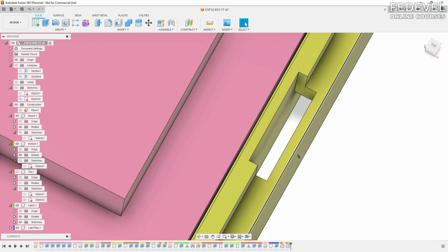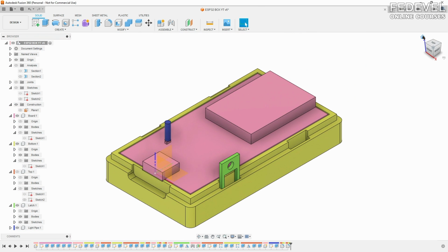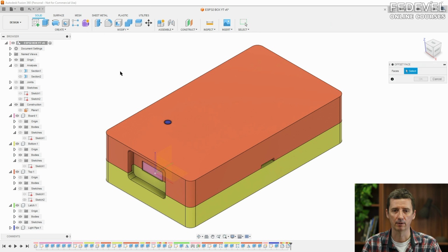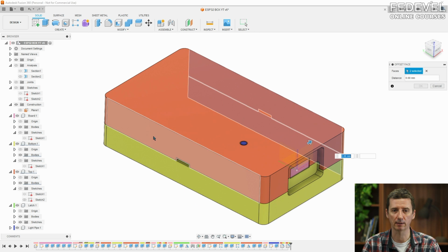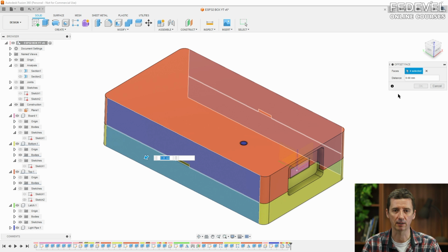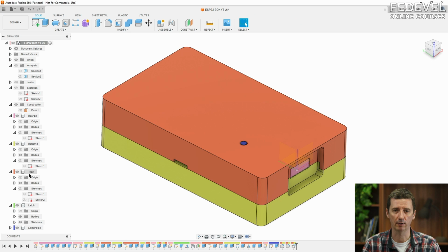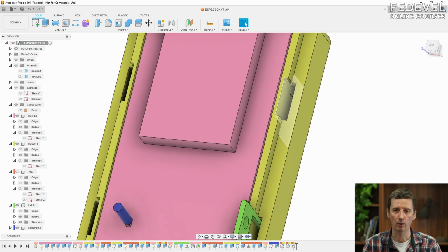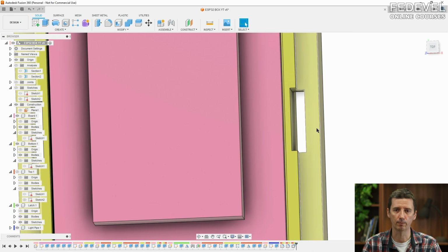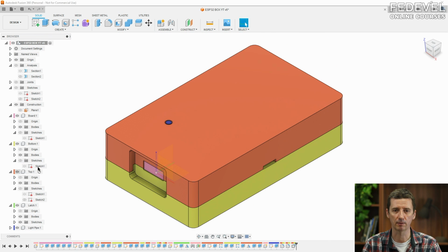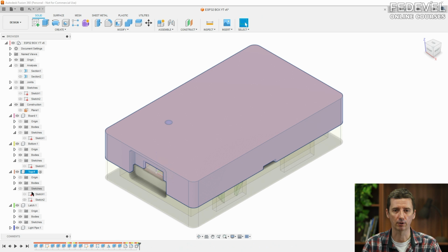This is too thin. When I 3D printed this box, I found out the holes are visible on the side, so I'm going to make these sides a little bit thicker, 1 millimeter thicker. When you have a look now, the wall is a little bit thicker, so the hole is not so visible when the box is 3D printed. And also we would like to add text on the top of our box.